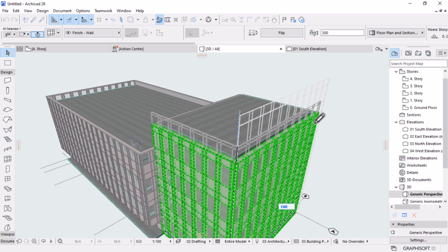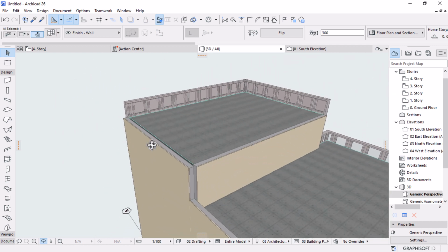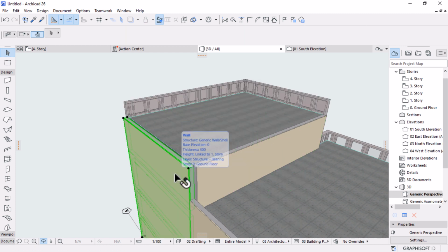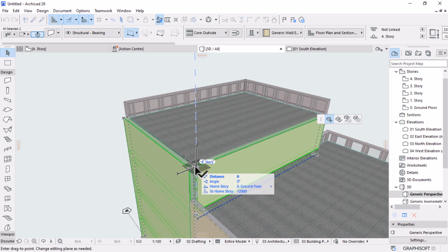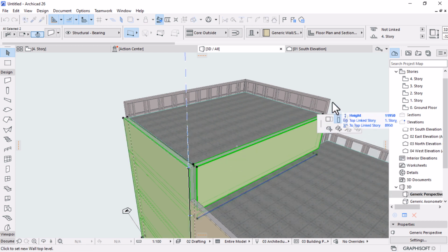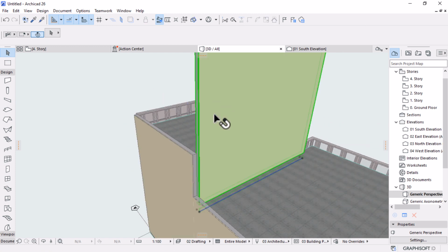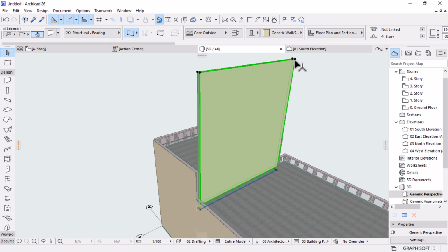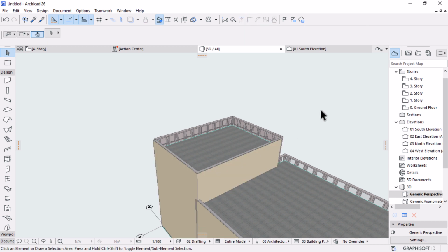Wait for it to compute. Perfect. And then I can come this side and do the same to these 2 walls. Stretch all the way. Stretch them using the stretch height and reference with the height of the curtain walls. Oh, sorry about that. This decided to go all the way, so let's bring it back to here, and we can select these 2 and then fillet to clean up this corner, something like that.